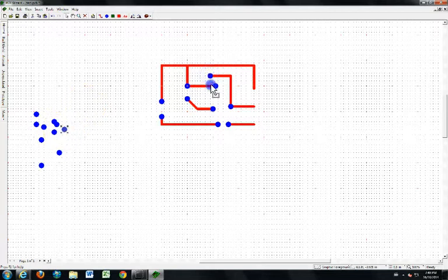And just about done here. The pads kind of snap to the grid in the background, which is kind of nice. You can put it wherever. Okay, so you can see I made a couple too many pads. Not a big deal. I'm just going to left click and drag a square around them, select them, and then go up to edit, delete.